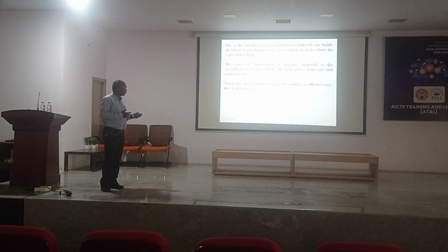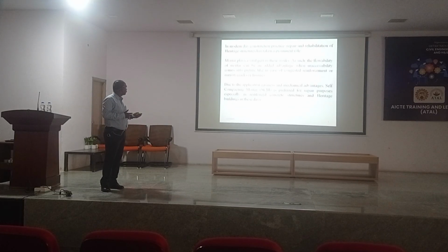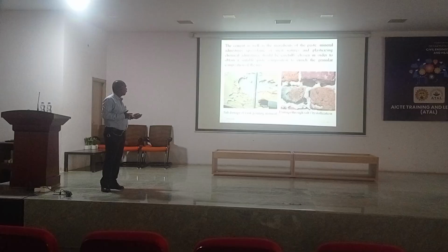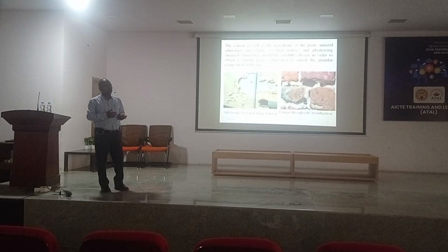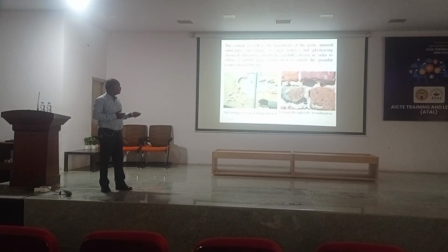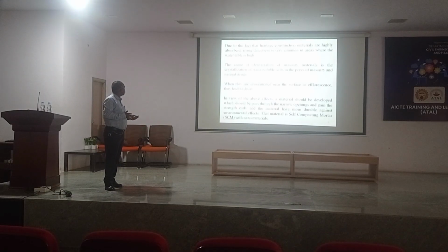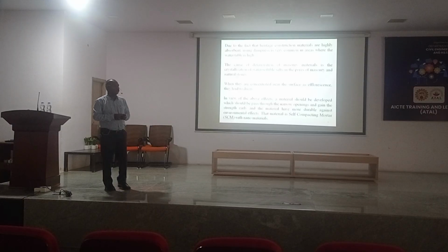In the photograph, damage due to salt crystallization. The mortar is damaged, and this is efflorescence, that means salt damage. These are the major problems in this salt crystallization process, and efflorescence leads to decay. These are the reasons for it.